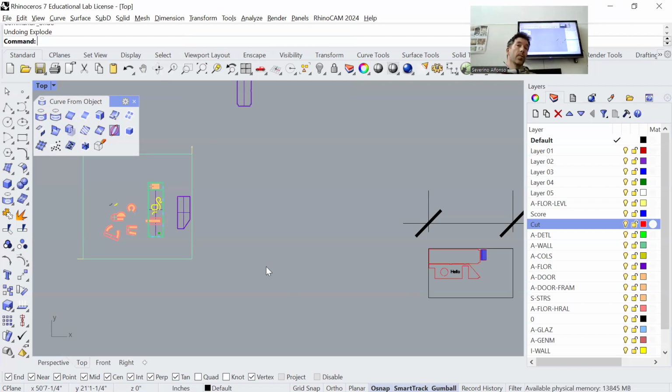That can be done in Grasshopper, for example. But you will need to select the surface that you really want and embed them into Grasshopper and do the whole process there. So Grasshopper could definitely help out with a more automatic process. I would recommend it with very complex models, but with an interior design model like this one, I don't think it's necessary. Do your exporting process carefully and go for it.